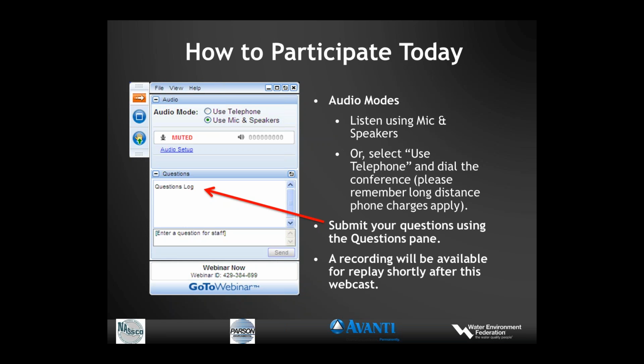Okay. And I'll throw the last one out there. Are there other methods of sealing at manhole and service connections? Right now, the best method at manholes are the hydrophilic rubber grout or the hydrophilic rubber gaskets. If you don't use those before and you want to seal after the fact, after installation, grouting is about the only way that I'm aware of. As far as lateral connections, there are the cured in place top hats and full wrap connection sealing methods. There are also grout, several effective grout methods that can be used.